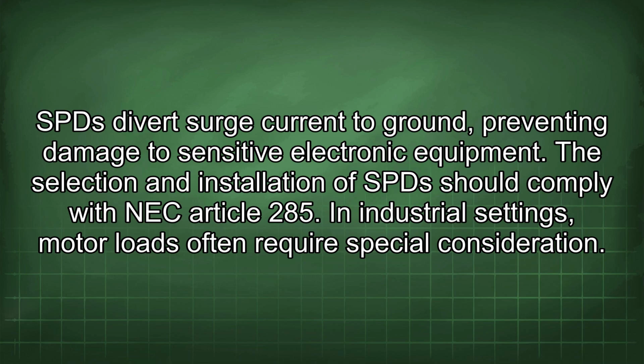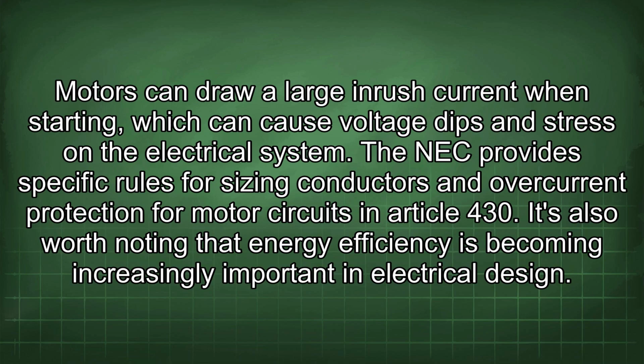In industrial settings, motor loads often require special consideration. Motors can draw a large inrush current when starting, which can cause voltage dips and stress in the electrical system. The NEC provides specific rules for sizing conductors and overcurrent protection for motor circuits in Article 430.